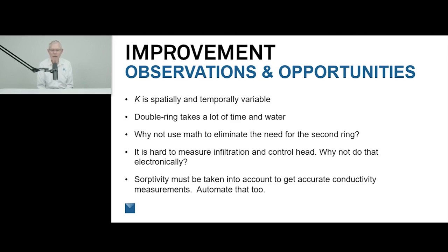It's possible to simultaneously measure infiltration rate and control head, but it takes a team of two well-coordinated people to do it properly. By doing that electronically, you get a quick return on investment. Finally, and this will make better sense in a few minutes, we need to appropriately account for sorptivity. The matrix-driven flow is part of the infiltration, and I'll show how we automated that.